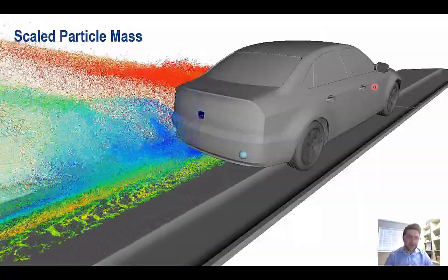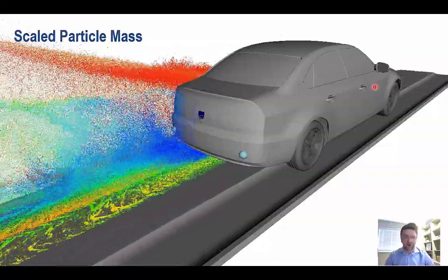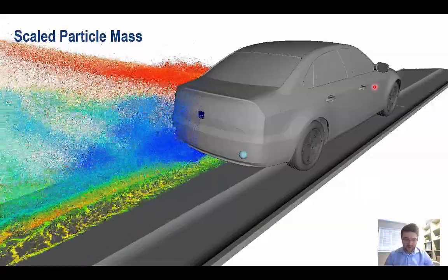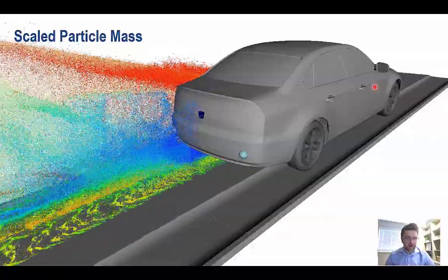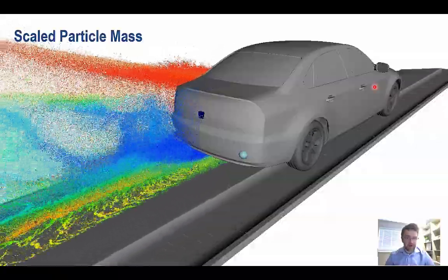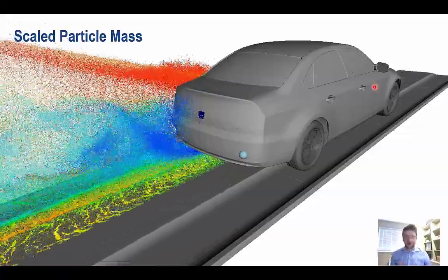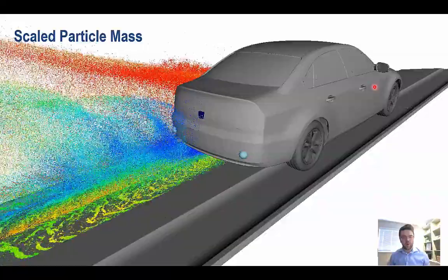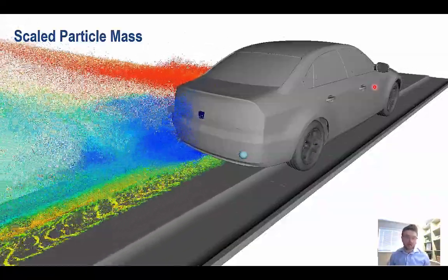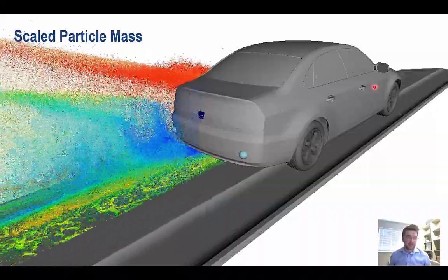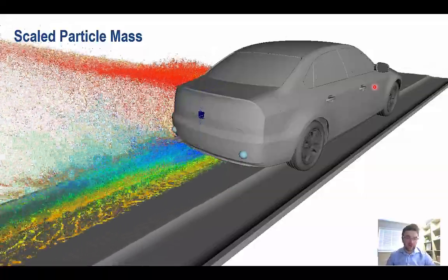So what this means is that the effective mass of the particles is scaled to that of a particle of diameter 0.6mm, and also the surface area, so that the amount that the airflow affects the particles is also scaled. This allows us to create the effect of the very light particles without the requirement of simulating those small particles, which would take far longer, and we wouldn't be able to iterate the design nearly as much as we could for these large particles.